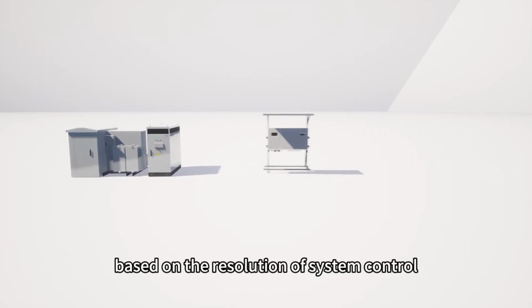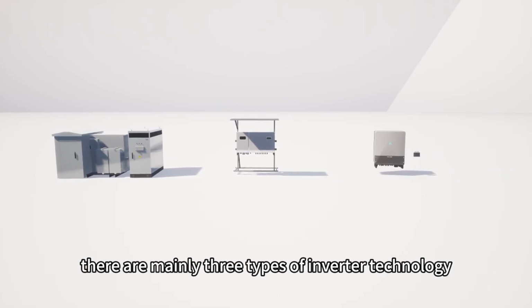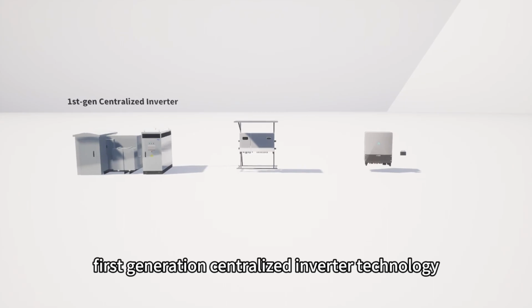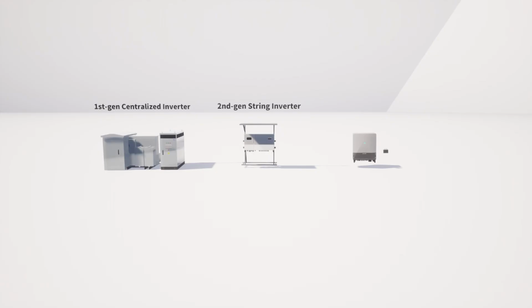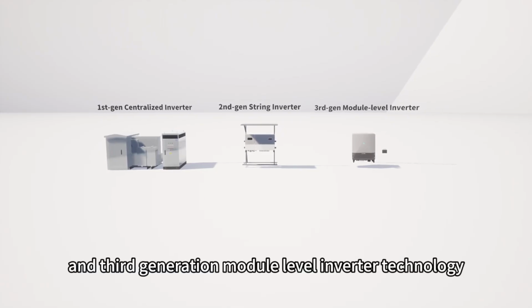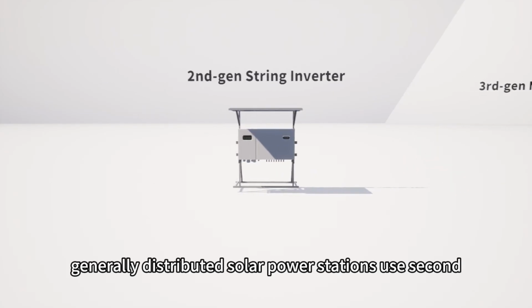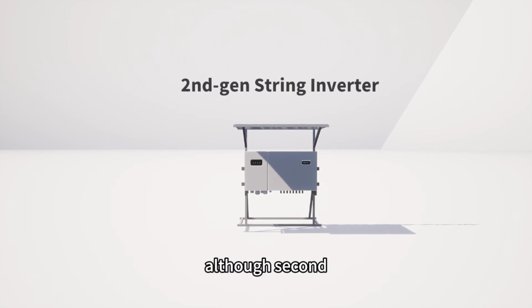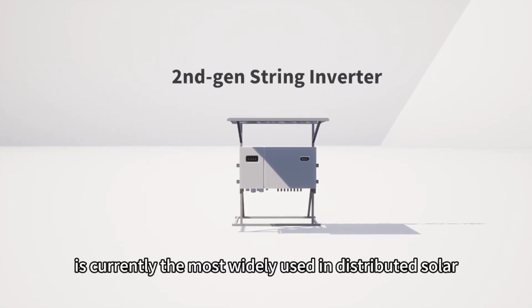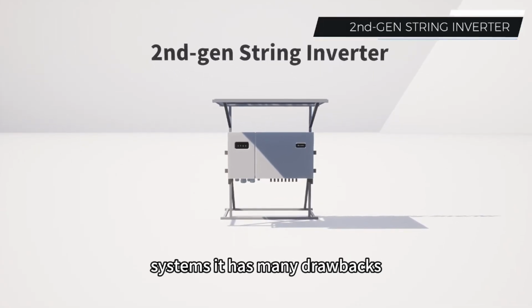system. In current solar systems, based on the resolution of system control, there are mainly three types of inverter technology solutions: first-generation centralized inverter technology, second-generation string inverter technology, and third-generation module-level inverter technology. Generally, distributed solar power stations use second- and third-generation inverters. Although second-generation string inverter technology is currently the most widely used in distributed solar systems, it has many drawbacks.